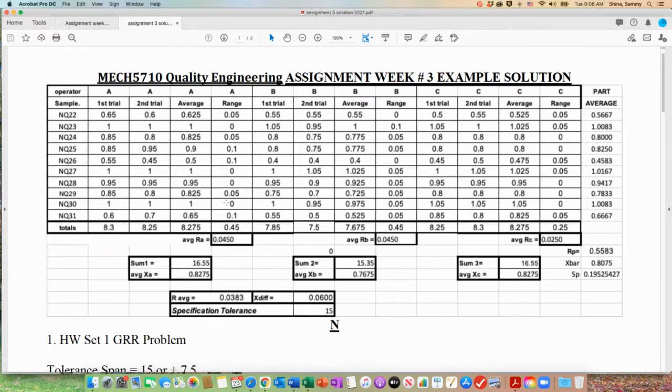So if there's a mismatch between the supplier's equipment and operator measurements and the incoming inspection at the company, a part that would look correct within specification at the supplier might be out of specifications at the company. So GR&R is an excellent way of resolving these problems. In the industry, it is generally accepted that the error due to equipment and operator is less than 10% of the measurement. So that is the standardized way of measuring it.